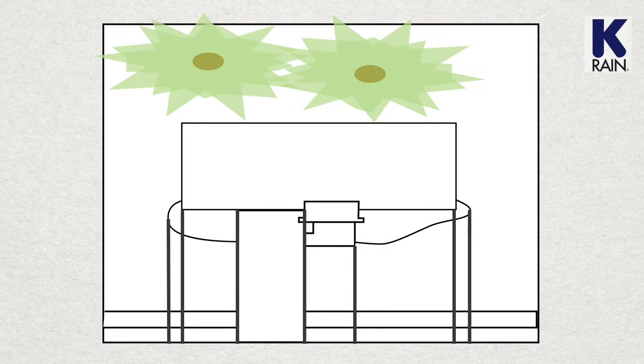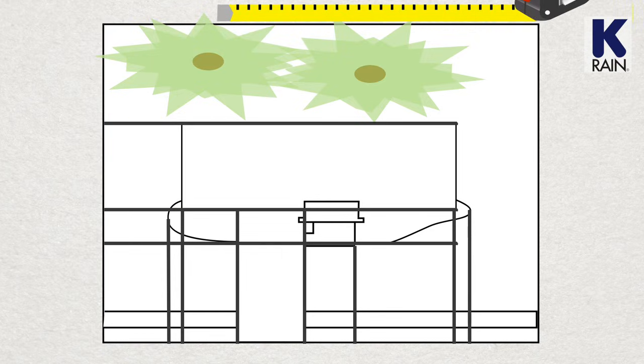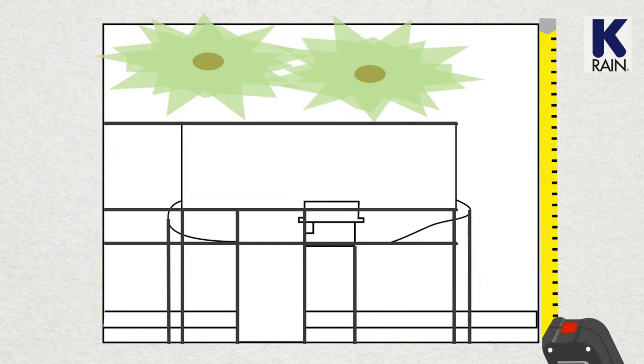Once you have measured the property from the curb, repeat the process with the measuring tape stretched along the side of the property at a right angle to the curb. You'll now have two coordinates for everything on the property, and you will be able to easily draw the property to scale on your graph paper as you go. For houses with complex back or side yards, you might need to repeat the process along the back edge of the property and on the other side, but 2 passes are sufficient for most properties.